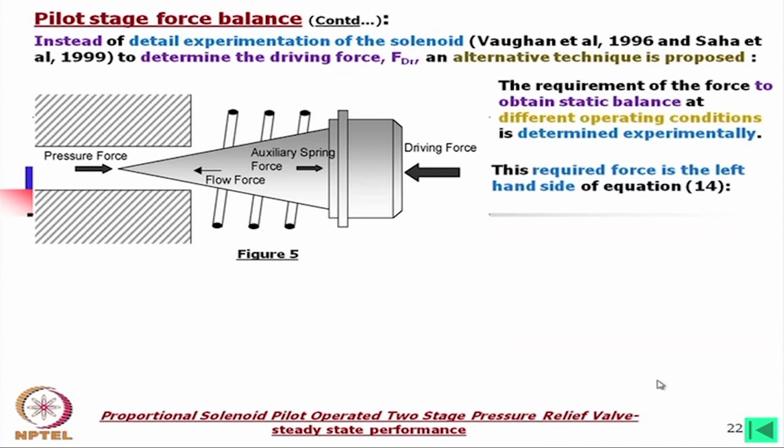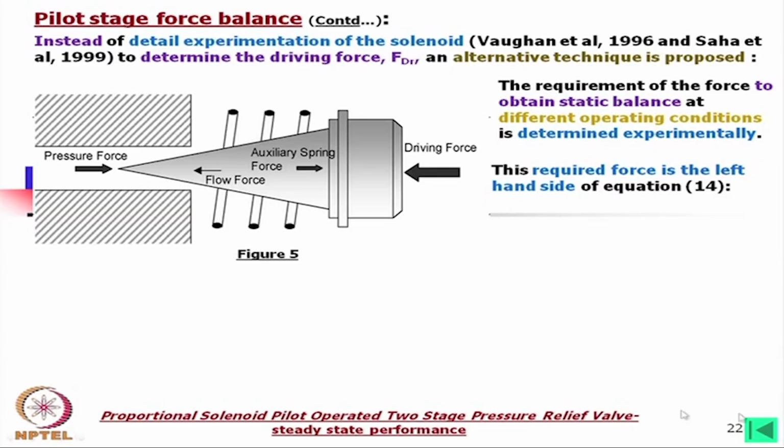Then, to find out this force for a valve, calculating all such meticulous things, you may not find exactly what the force will be. The best thing is to go for an experiment and see how much force is really there.